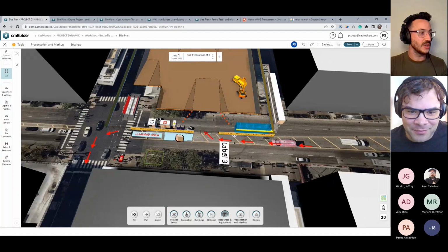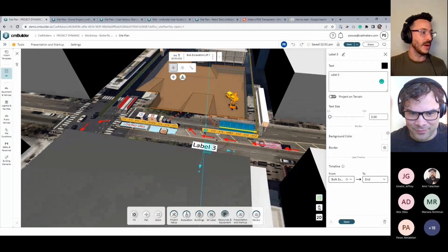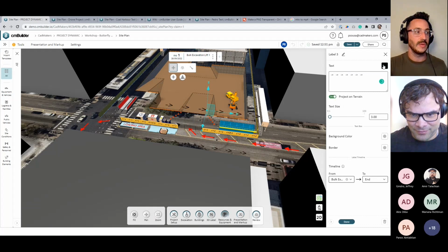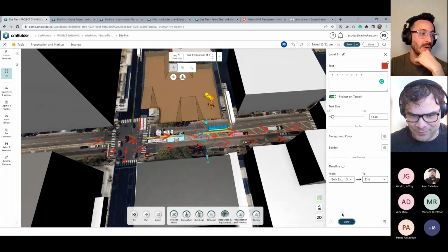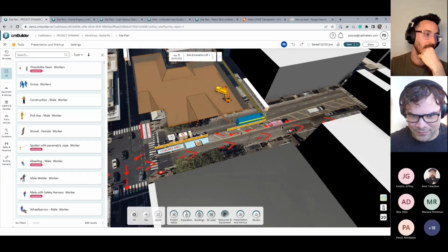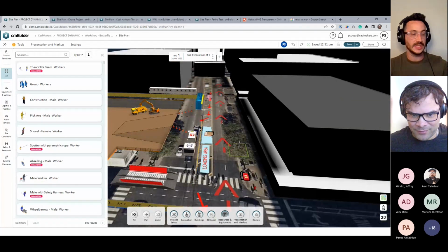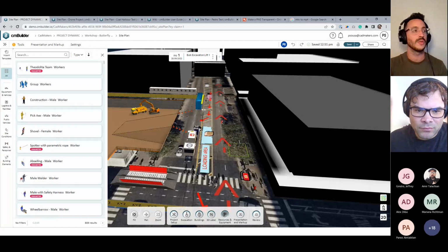Yeah, I also like to use that as arrows. So if I want my arrows to be projected on the ground, I can just put in a specific arrow over here, project that on the ground, remove that, and set up a size for it, and so on and so forth. Right. So if you're working with topographic terrains and the arrows that are in our site are not good enough because they're being inside of the terrain, you can use that as well to project that on your site.